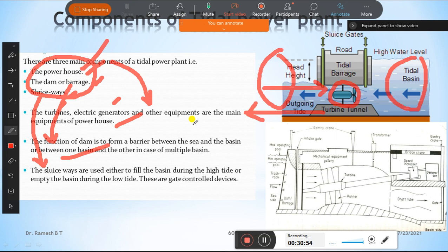And the barrage needs to provide a channel. The barrage or dam needs a channel for the turbine, which is completely made of pre-stressed or reinforced concrete. To build these channels, a temporary small dam is necessary, but it is now possible to build them on land, float them to the site, and sink them into place.